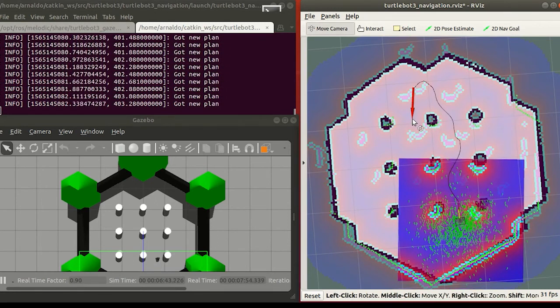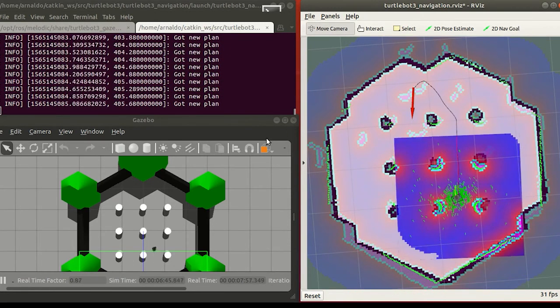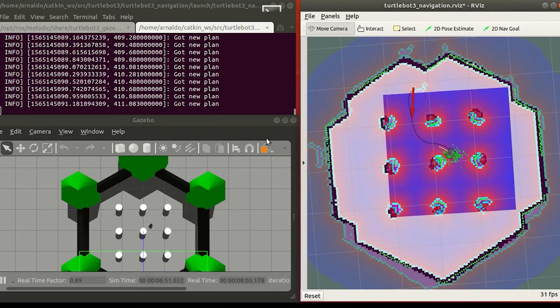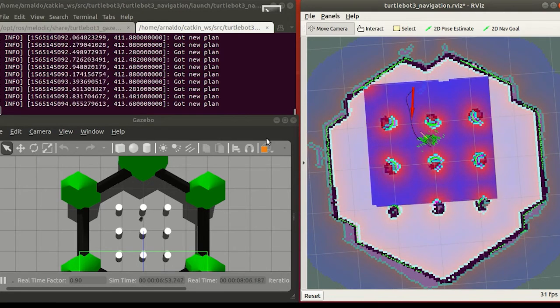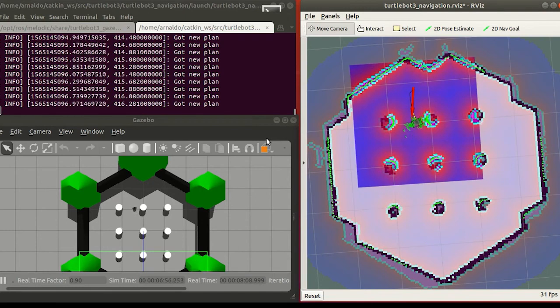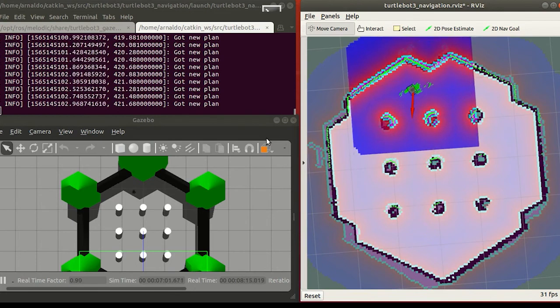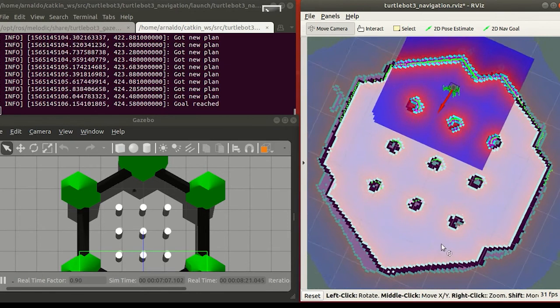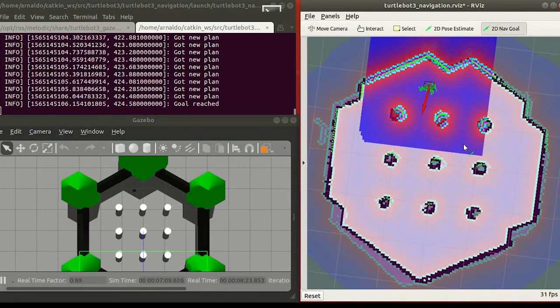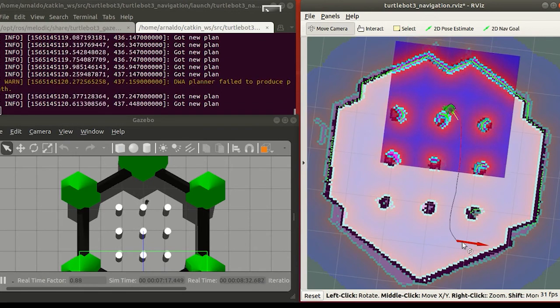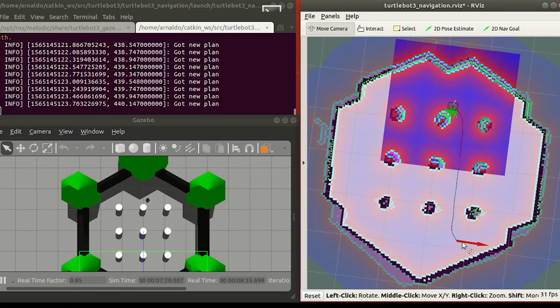After that we are just going to give it a goal, and it will create a path automatically, that you can see is getting updated continuously according to where the robot is and its surroundings. And you can see the green dots. Those are just arrows, not dots, but those arrows are getting concentrated at the center. That is, the error is getting low, and you can see around the obstacles there is a red inflation.